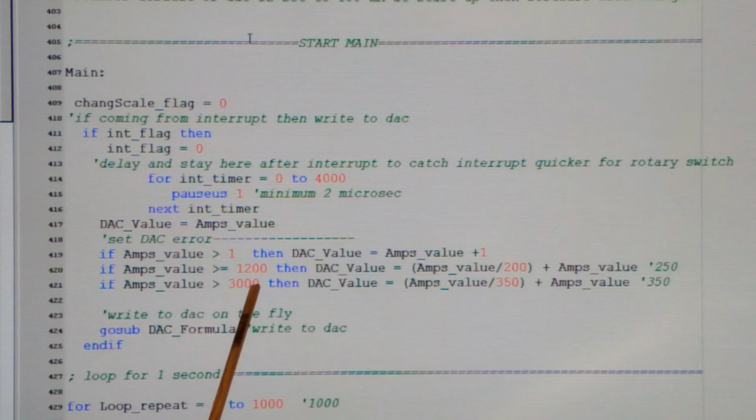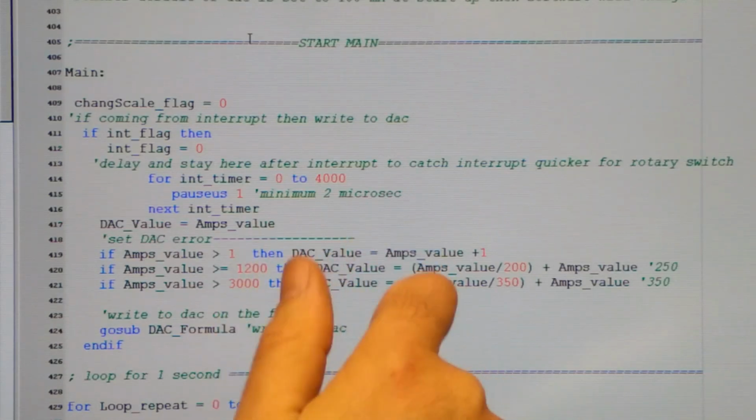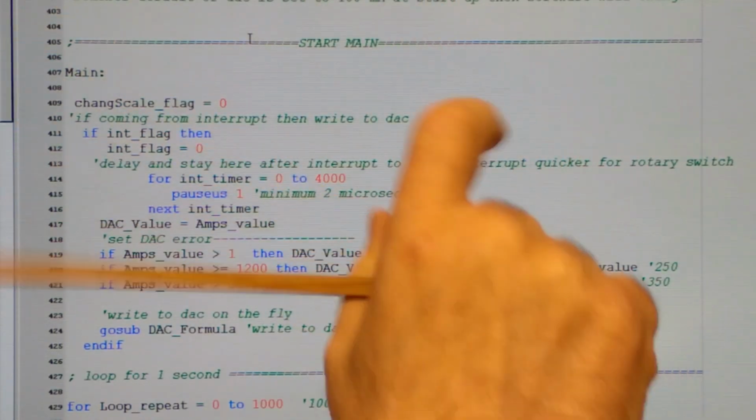So because of that, while it's writing to the screen, when you change your rotary switch, it's not going to go to an interrupt because you switched the interrupts off. Yes. So since I am doing that, what I do is I pause the code in this loop. I do a for loop here, okay, to wait to see if you're still turning the rotary encoder.